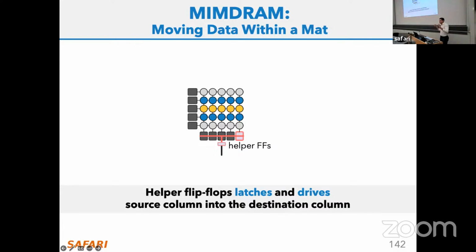I like to think about it, it's not correct, but as yet another sense amplifier, which is a bit stronger than the previous one, but I don't have as many of those as I have local sense amplifiers. Here I have 12 of them, and here I have only 4. So I can make a stronger circuitry without consuming much area because I have fewer of them.